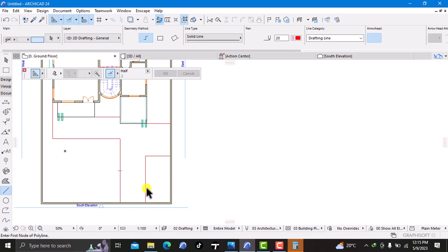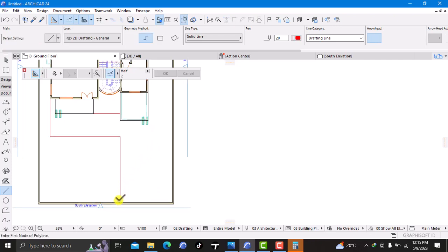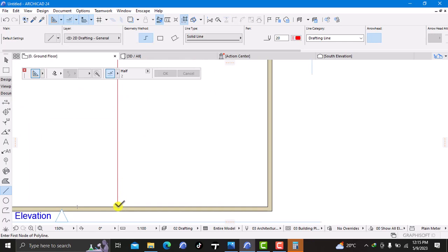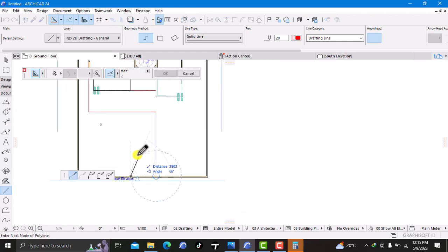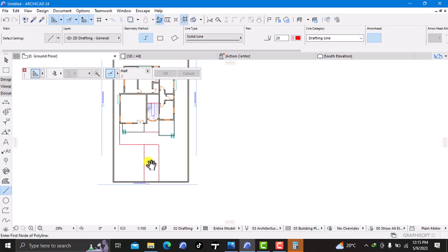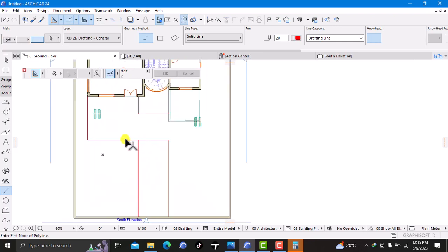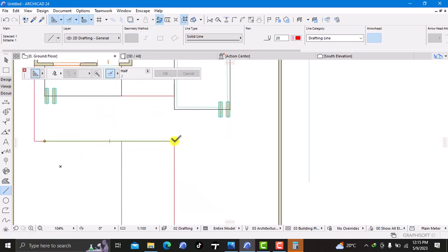So even the gate, I'll have to shift it so that I can allow more ground over here. And just delete that. And basically from here I can drag the gate this distance of 3500. Enter, and basically drag this to this point over there, and then from that point now I can readjust this line over here to somewhere over there.